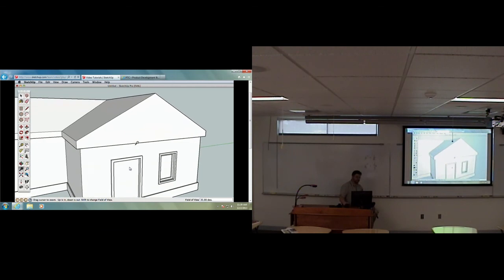To finish our house example, let's turn our attention back to the roof and some drawing aids in SketchUp. Use the Line tool and start drawing a line from this edge. Now hover over the roof edge for a few moments, and as you continue to draw, you'll see a new inference that is purple in color and parallel to the edge we just hovered over. We can easily find out how far to draw this parallel edge by hovering over the ridge point to focus attention there. Then as we come back to drawing our original line, SketchUp will tell us where these points meet up.